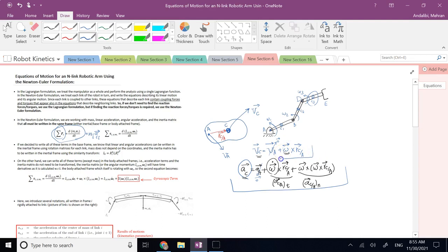So through velocity analysis, you try to find omegas really, and you need omegas definitely in your acceleration analysis. So we always do velocity analysis, then followed by acceleration analysis to give me A's, and masses are typically given. Then I can find the forces on the rigid body, including the pin forces.